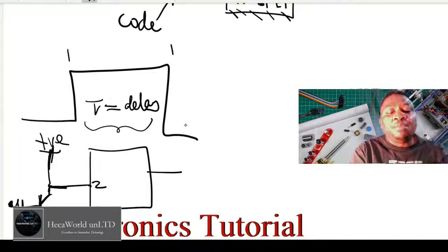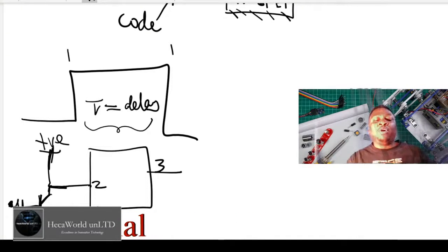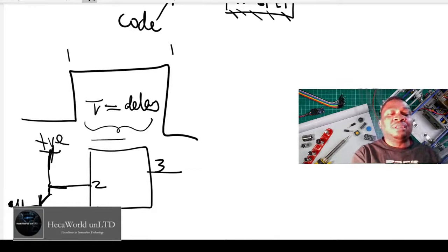That means whenever the output, which is pin 3, is high, you use that to block other flip-flops from resetting all the flip-flops. So whenever you try to set it, it will reset right away. You do that until this monostable interval is out, and then the person can try again.